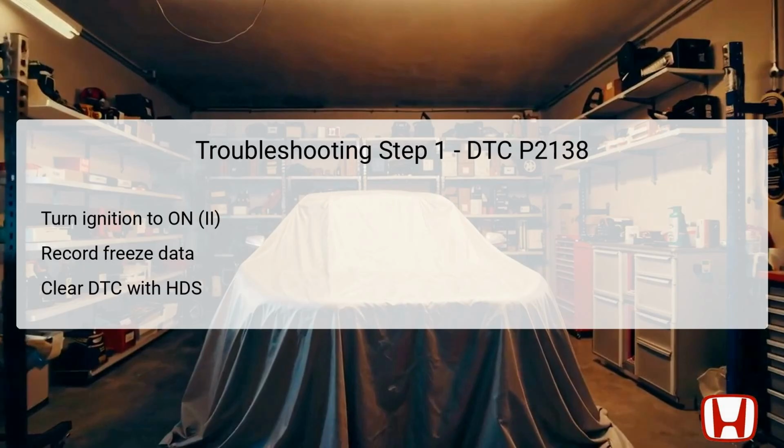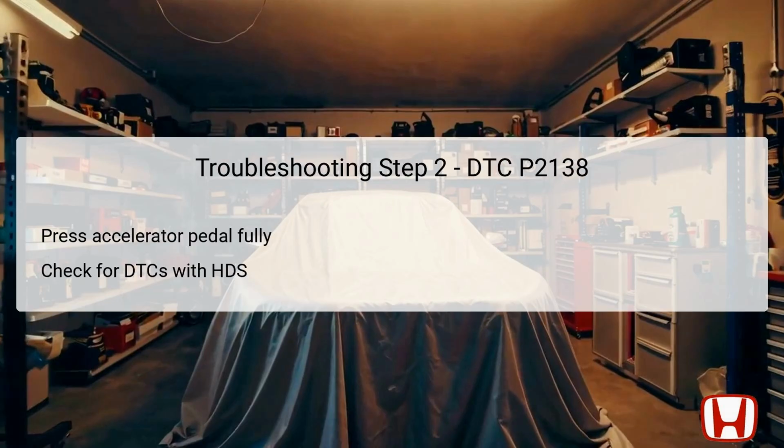Following this, clear the DTC using the Honda Diagnostic System, HDS. Clearing the code allows for a fresh start in diagnosing the problem, revealing any persistent issues that may indicate a more serious fault. This initial step is crucial for ensuring that all diagnostic readings are based on real-time data rather than lingering stored codes. Next, fully press the accelerator pedal to the floor.